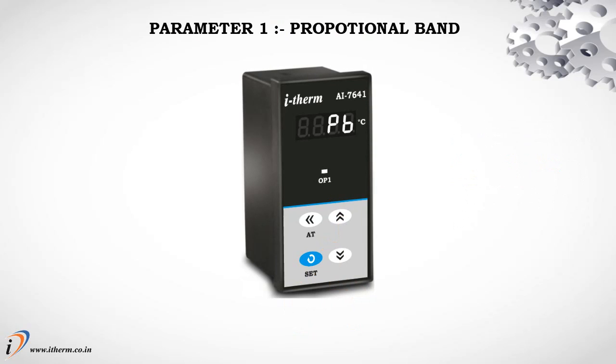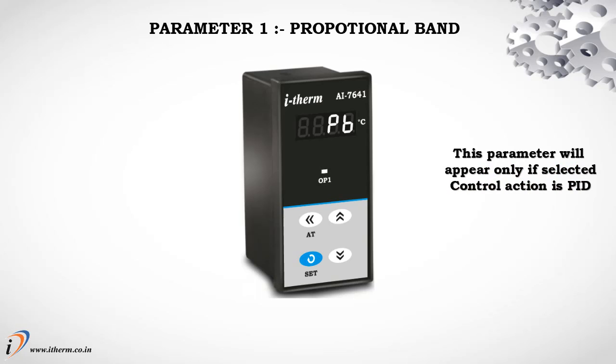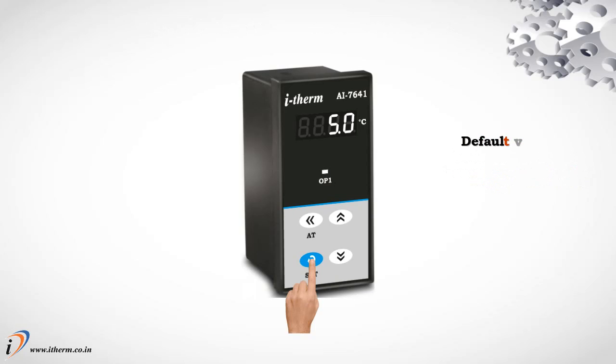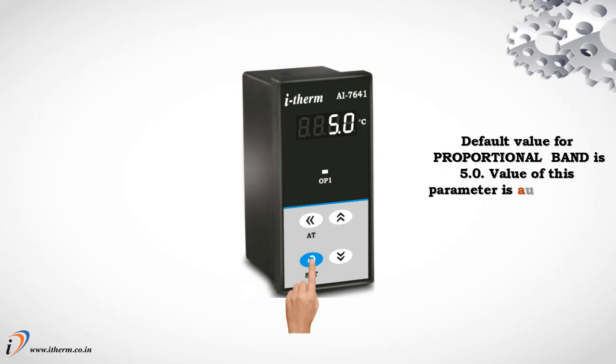Parameter 1, proportional band. This parameter will appear only if the selected control action is PID. Default value for proportional band is 5.0. The value of this parameter is automatically set by the auto-tune function.